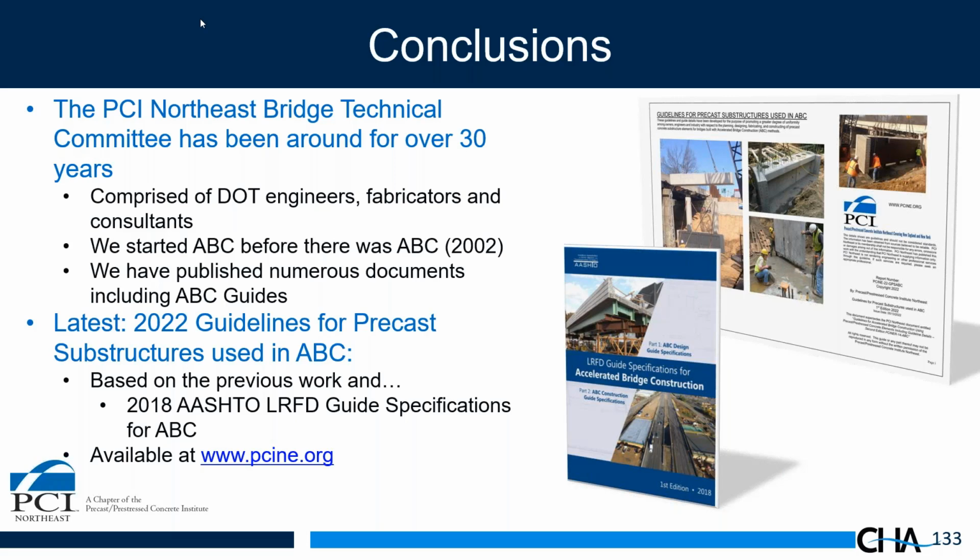Okay. What type of mechanical connectors have worked better in construction? Now, the grouted couplers work well. You have to be tight with tolerances. You have to make sure your tolerances are correct. But they have worked. They've been in the industry for probably 40 years. They're not a new technology.